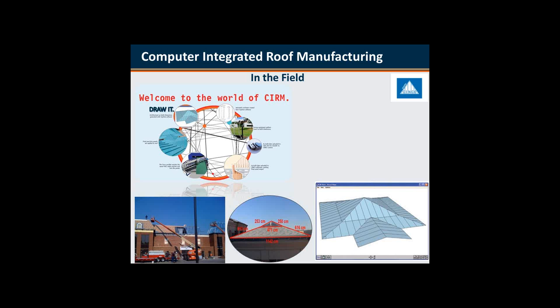You could think about some types of warping. You can think about the steel bolts in the cement not setting properly, which cause some skewing errors and basically unlevelness. But it happens every day, and you can kind of see it in this diagram at the bottom here. You see differences in measurements on the left side and the right side. So it's important that they go up and get those as-built dimensions so they can compare to drawn, and then they can fabricate the panels the way that they need to.